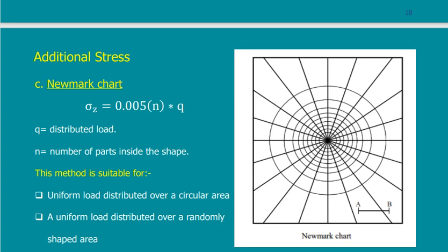And I will just take this square, put it on top of this Newmark chart at the location where I need to calculate the stress.